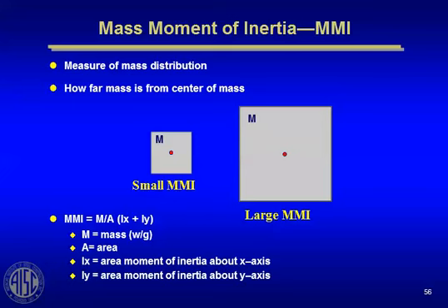Torsional instability is a bigger problem for seismic perhaps than it is wind. That's when you see the damages during earthquakes. So the seismic provisions have what they call torsional irregularities that they make you design for and check. We also have a similar problem in a wind condition. We don't want our buildings under wind load to be doing a torsional oscillation.